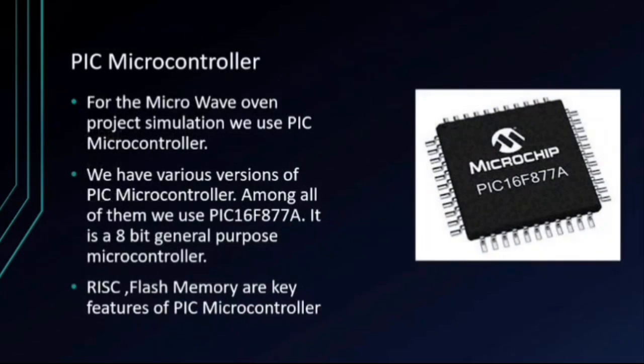PIC microcontroller. PIC stands for Peripheral Interface Controller. These are 8-bit general purpose microcontrollers. For the microwave oven project simulation, we are using the PIC microcontroller. We have various PIC microcontrollers. Among them, we are currently using the PIC 16F877A, which is an 8-bit general purpose microcontroller.